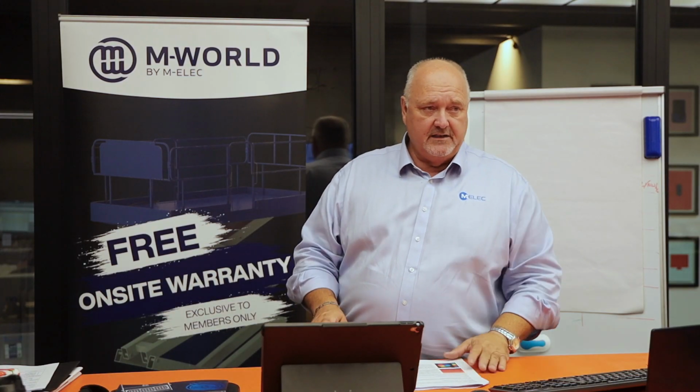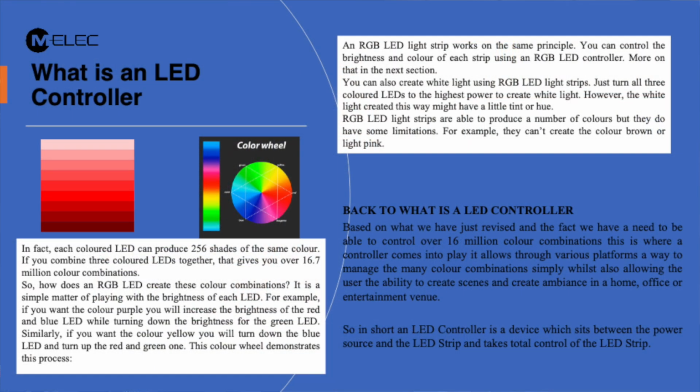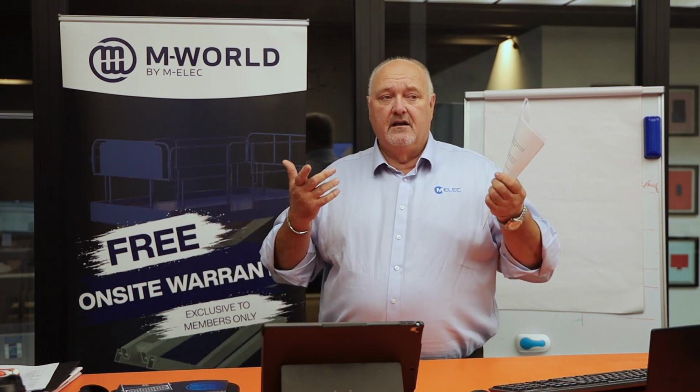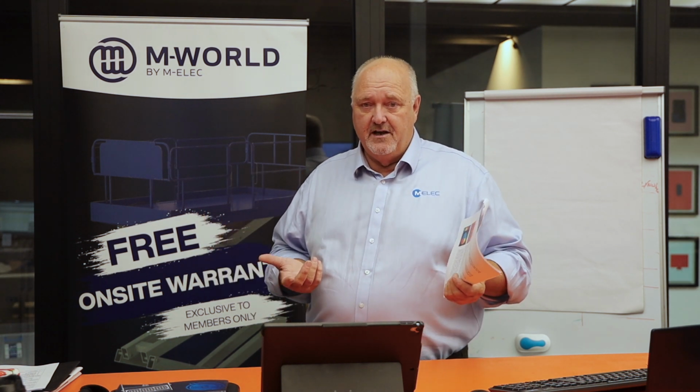So when we look at this, and when we look at the spectrum, a controller is used to actually allow us to go through the color wheel. Okay, there's a couple of examples here of the color wheel and the 256 shades of each and every color. So when you combine the 3 LEDs, it gives you 16.7 million color combinations. All right, so we can't control that with anything analog, so we need a proper controller, and this is what it means.